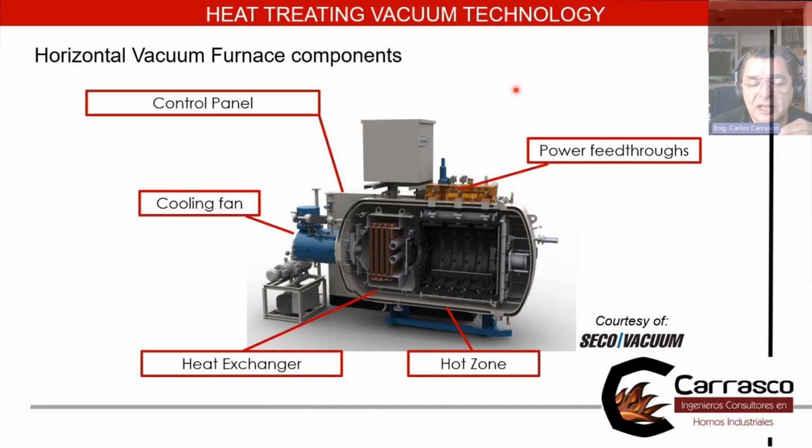No, because in real life, the materials have cross sections that I have to manage, as I don't want to crack any part because they are very expensive. So I have to create recipes where I heat up, hold a lower temperature, then slowly heat it up again, and then hold the temperature, sometimes 3 times, like H13 steels require. Machine parts require a lot of steps for heating.